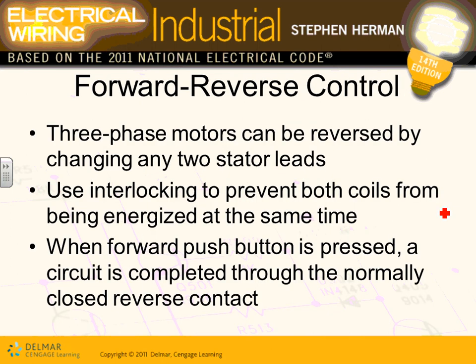Okay, so there are also forward-reverse motors, guys. Motors are so important because they can move air, move oil, move water, move what else? Cut things, right? But sometimes we also need to move the air in or out of the room. What do you need? You need to reverse the motor. So there's reverse and forward. In order to reverse and forward, you need two starters. We'll see in a second.